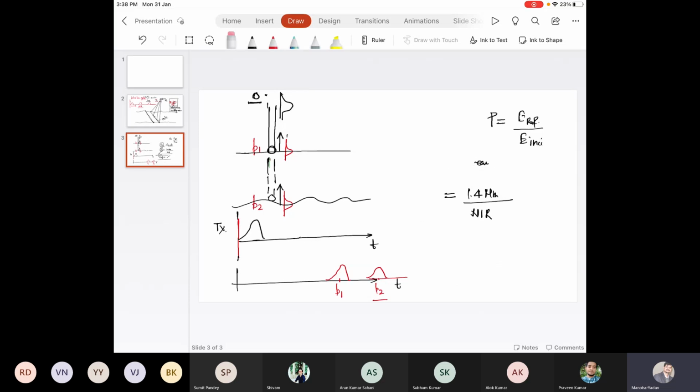I hope now it is clear to all of you why we do not use an IR band for bathymetric application. Why we decrease the wavelength so that it is in the visible spectrum. The reason is, very clear, that water has a reflectance only in the visible spectrum. So in an IR band, there is no reflectance. What will be the problem when we don't have a reflectance? Can anyone tell me, let's say a beam is fired and it is completely absorbed. Why can't we calculate the coordinate of that point?